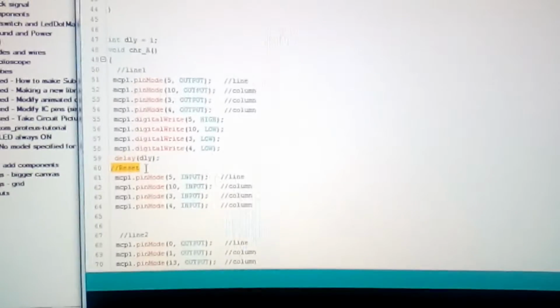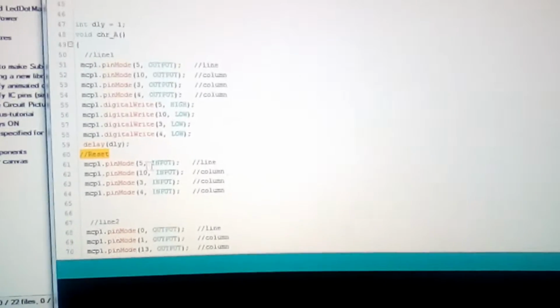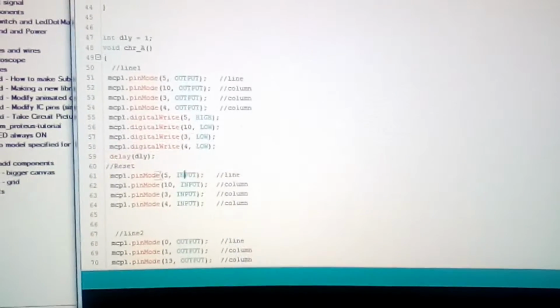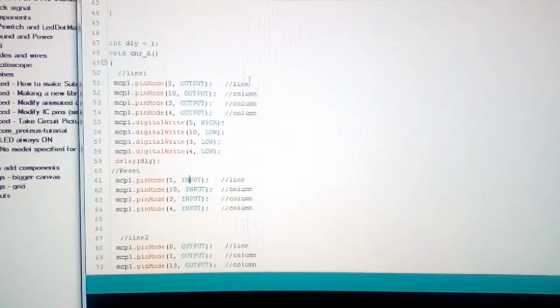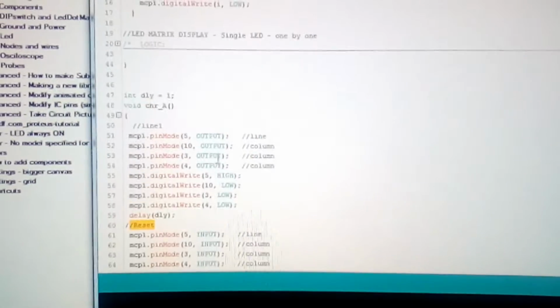And here in version B, I have this reset function commented out. I ignored it, and what I did, a very smart move actually, I implemented the switch from output to input directly per each pin, not through all pins like I did in the reset function that I was calling in the first version. So now if I'm switching, everything is switched to input.